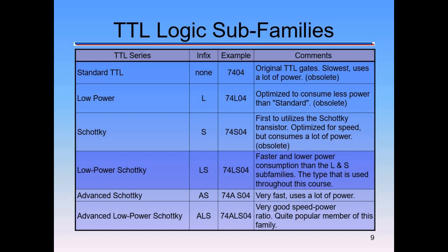But what we use is the low power Schottky, the 74LS04. As you've been wondering, using Multisim and doing a little bit of breadboarding with some of these and doing the AOI logic, you're like, why is it called a 74LS04? That's really where it comes from. They're faster, they have low power consumption, and that's what we use throughout the course, and what you're going to be breadboarding with.